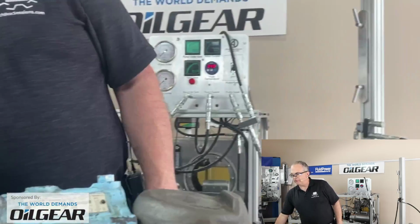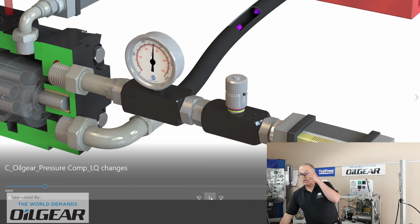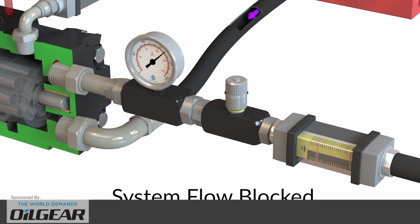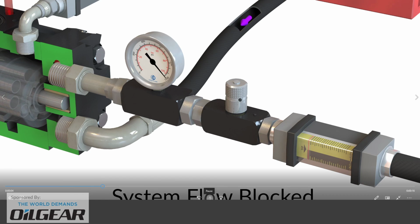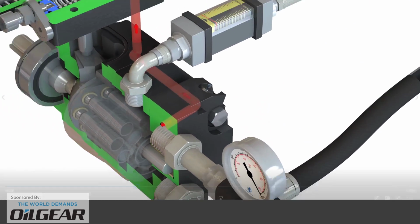Okay, so just to give you a bit of a picture there, we're going to start to shut in the flow rate coming out of the outlet for an oil gear pump here, block off the flow. You can see that our pressure spiked up, so our flow meter showed the drop off in flow and our system pressure spiked all the way up. And watch here, there is a passage from the outlet of the pump that's actually drilled right through a very thick pump casing and brought up to the underside of that pump controller.